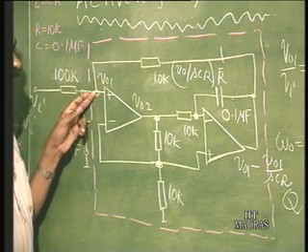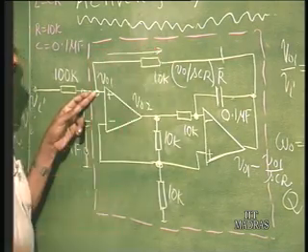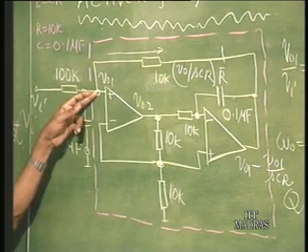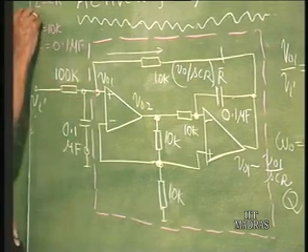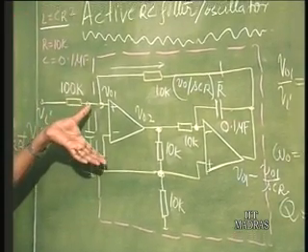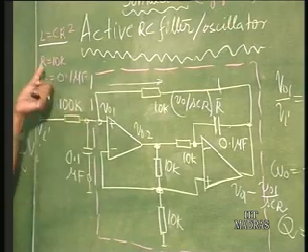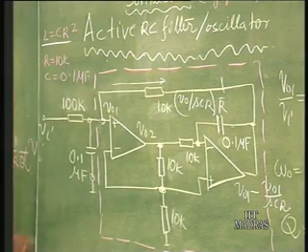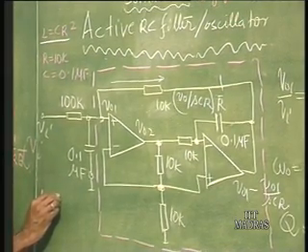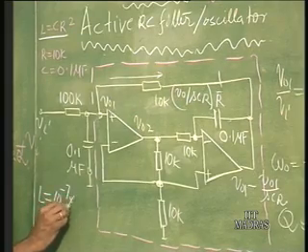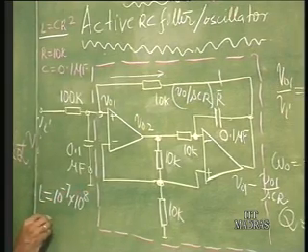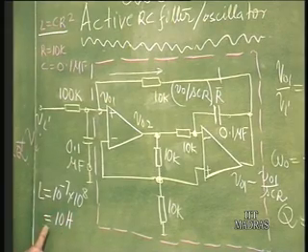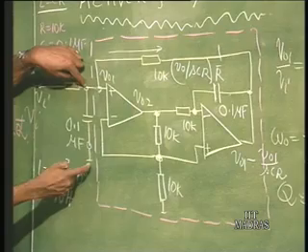which means it will give you a current of V naught 1 by SCR squared, which means the current in this is going to be determined by SCR squared impedance, okay, which is nothing but an inductor L equal to CR squared. So, this simulates an inductor L equal to CR squared. C in this case is 0.1 microfarad, R is equal to 10 K. Okay. So, it will now simulate an inductor L equal to 10 to the power minus 7 into R squared 10 to the power 8, which is actually speaking 10 Henries. Okay. 10 Henries of inductor is simulated from here to ground.